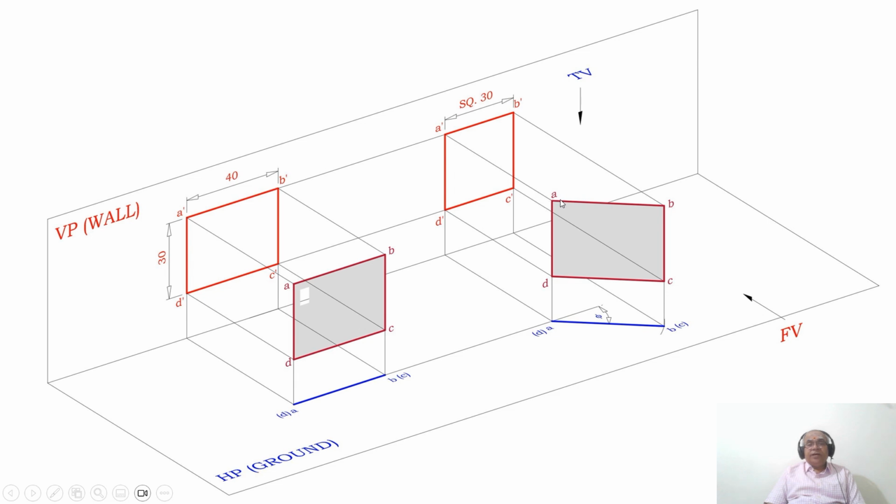That is what we have shown here. As we rotate this AB, you can see that the length of A dash B dash, which was 40, starts decreasing. Till what distance will it decrease? Till it becomes 30. Once you get 30 here and also 30 here, obviously it should stop at that particular point.